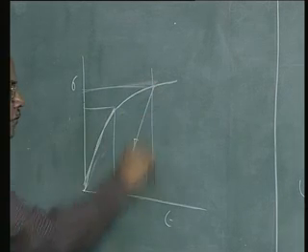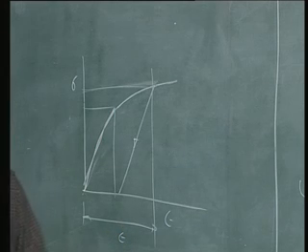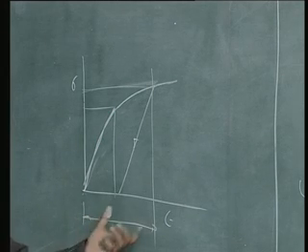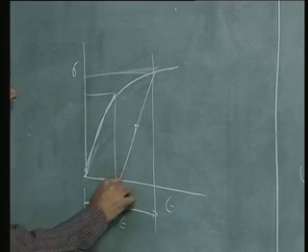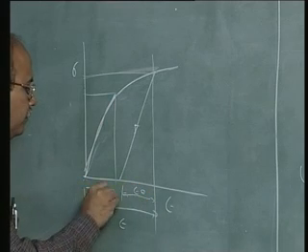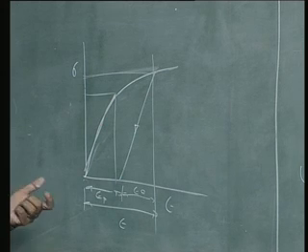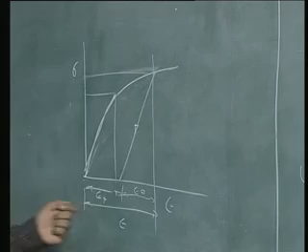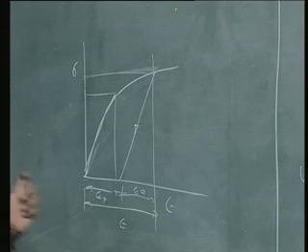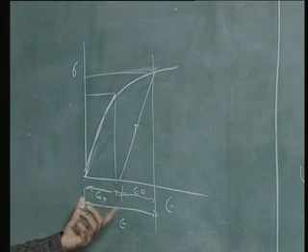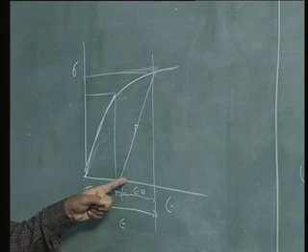So if this is the strain from which I am unloading, then I have a recovered strain, which I call epsilon E, and the permanent strain, which I call epsilon P. So epsilon E plus epsilon P. I think some of this we have done in the previous course, it doesn't matter, for continuity let us go ahead and do it. So the first thing that I want you to understand is that these strains consist of elastic and plastic parts, and that the unloading is an elastic unloading.